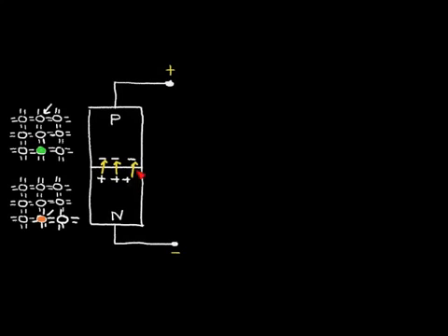And this region is the key to understanding the operation of the solar cell. Now let's say that we have some light that comes into this P region. And this light can knock one of these electrons out of this bond with a silicon atom, and it can produce a free electron and a free hole.